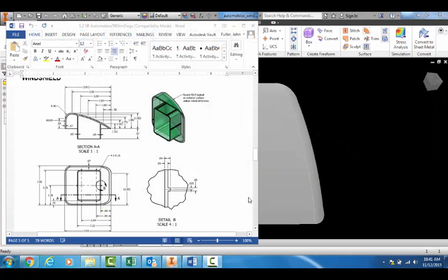Okay, now it is basically hollowed out. All right, so now that we have the main part of the windshield done, now we need to make this interior piece right here that kind of comes down through. Now the dimension we're interested in right now is this one, 0.67. Notice it is 0.67 inches down here in this height.